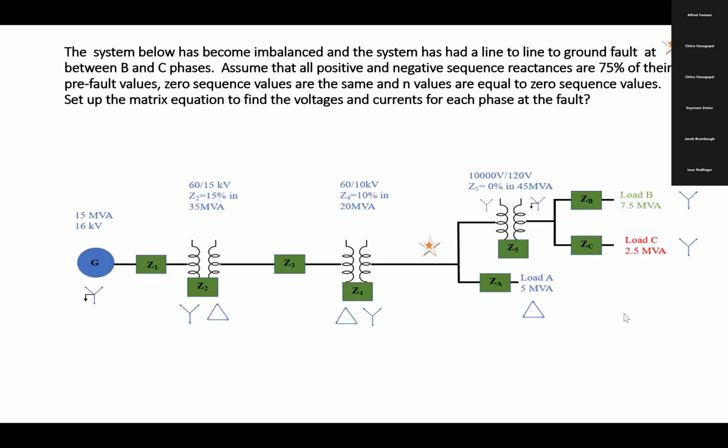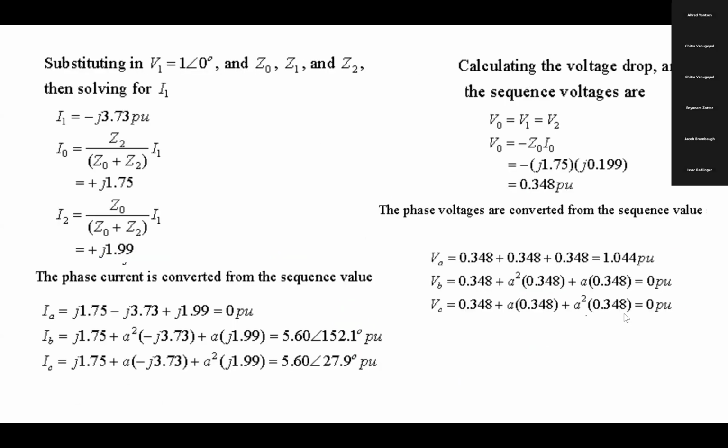right. So until this point, we have seen how to get the symmetrical components for each and every element of the power system network, how to calculate the fault, how to calculate the sequence components, how to connect them for each and every fault, and then how to identify the fault values, current and voltage. Now we are going to put everything together in a simple power system network and analyze each and every section independently. Okay. Do you want to take a break before that?